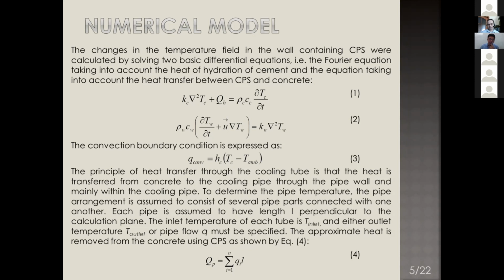To determine the pipe temperature, the pipe arrangement is assumed to consist of several pipes connected with one another. Each pipe is assumed to have a length perpendicular to the calculation plane. The inlet temperature of each pipe, T inlet, and either the outlet temperature, T outlet, or the pipe flow must be specified.